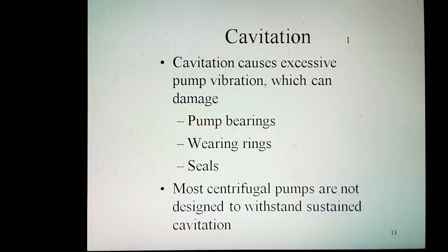Cavitation can also cause excessive pump vibration, which could damage pump bearings, wearing rings, and seals. A small number of centrifugal pumps are designed to operate under conditions where cavitation is unavoidable. These pumps must be specially designed and maintained to withstand the small amount of cavitation that occurs during their operation. Most centrifugal pumps are not designed to withstand sustained cavitation.